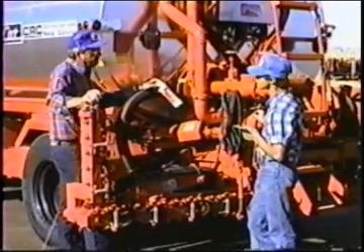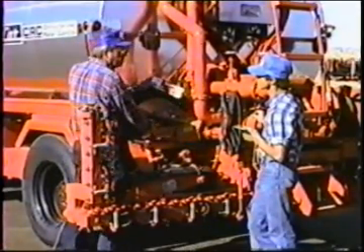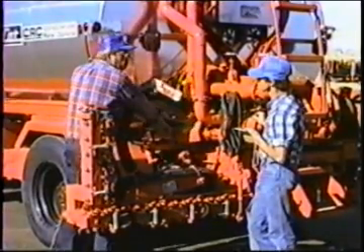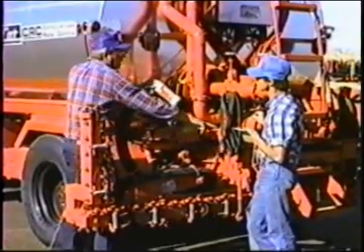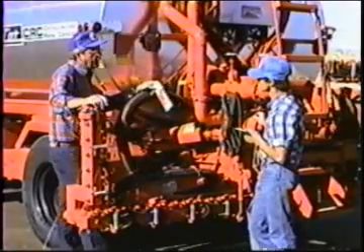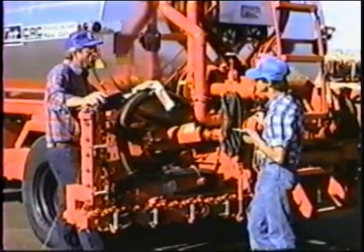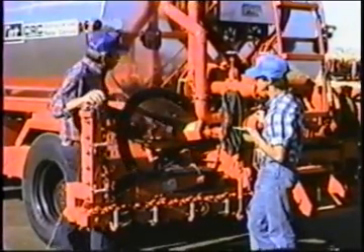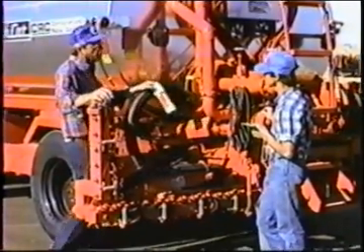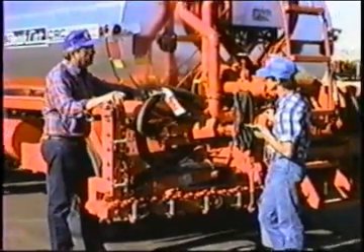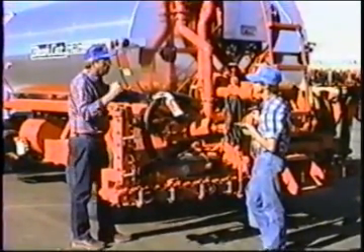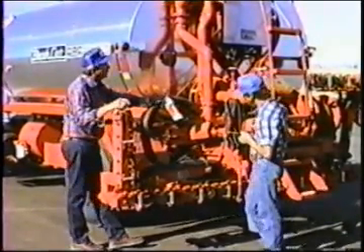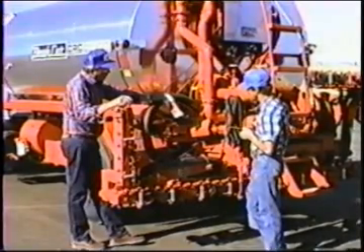In order to do that, we have used a hydraulic transmission to regulate the speed. That gives us an infinite number of gear ratios in the hydraulic transmission so that we can set that pump speed at exactly 135 gallons per minute when the truck is traveling 400 feet per minute. Infinitely variable ratio transmission essentially is what the hydrostatic transmission is. It's just like having a 10,000 speed gearbox. We can select the gear ratio in that gives us the exact speed for the pump at an exact travel speed. Now when we're spreading with the